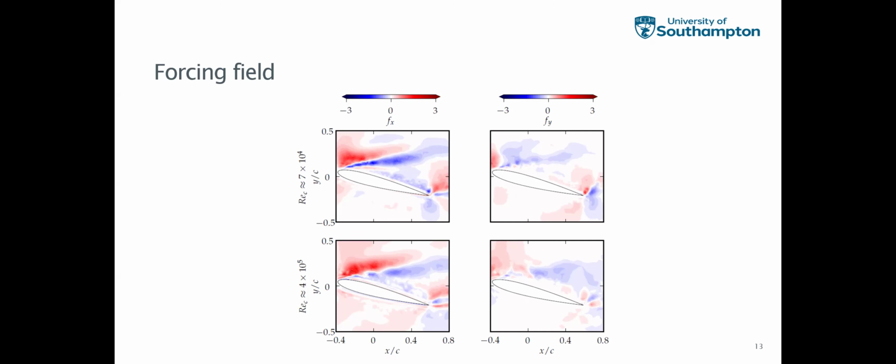So this really shows the areas where the forcing is acting, which is typically in the shear layer, which is also where the majority of the differences between the RANS turbulence model output and the experiments exist. So it was good to see that the forcing is being applied locally here, and it's what is improving the mean velocity field prediction, and not that it's being applied elsewhere and having a downstream effect. So this is something that we are working on at the moment.